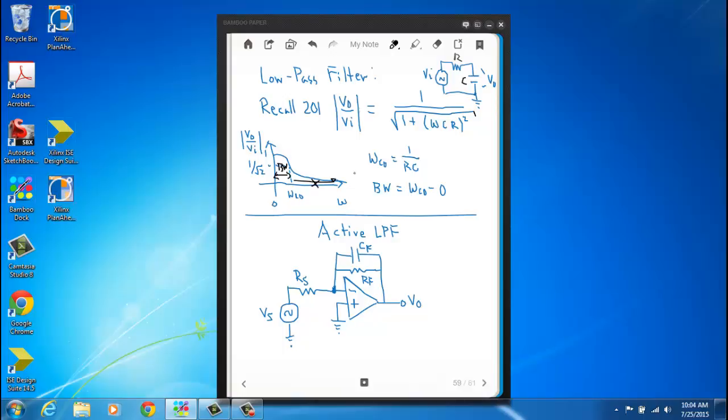So that's just a little review of a low-pass filter from circuits, and this type of filter is called a passive filter, where passive here just refers to the fact that V out can only be as large as VI. It can't be any bigger than that, and that happens at omega equal to 0 for this passive low-pass filter. Now, with op-amps, you can make what's called an active filter. In an active filter, with this op-amp, the magnitude of the output can be greater than the magnitude of the input, and that's due to this op-amp that has transistors inside, like we talked about, that have the ability to amplify. So here's how you make a low-pass filter with an op-amp.